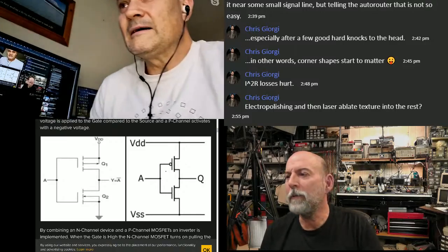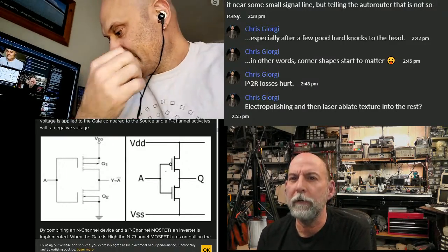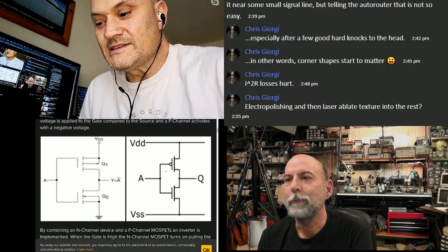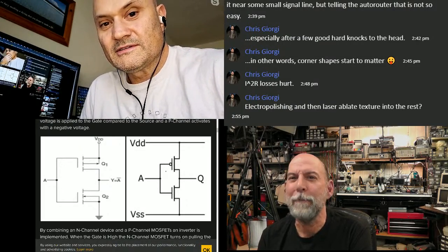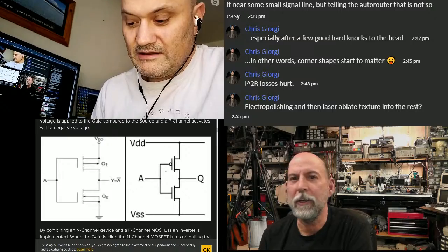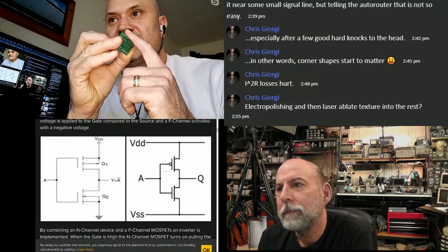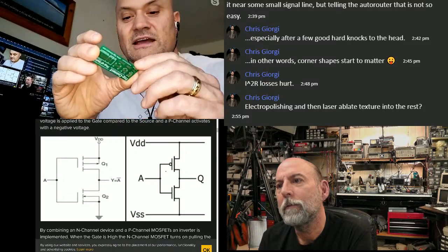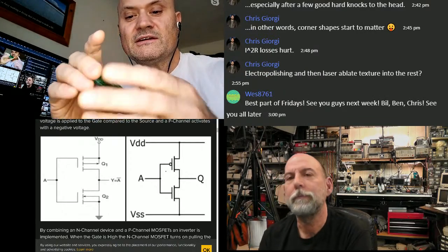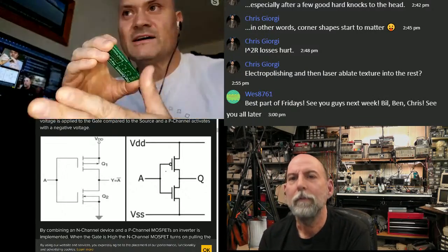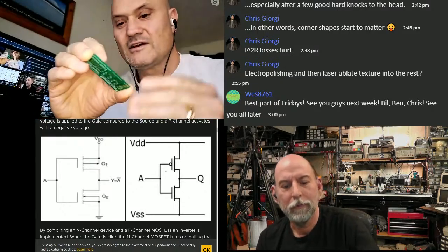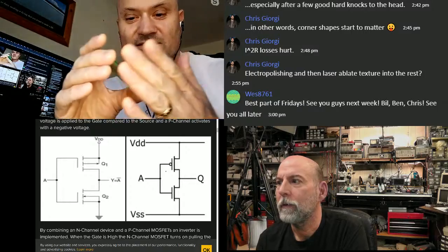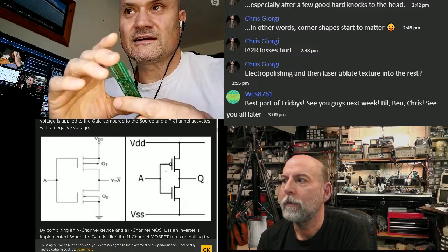So why wouldn't we use the edge of the PC board for a reference? Because the machine that cuts out the PCBs will be all over the joint. They're sloppy. Yeah. So you might be machining that and it'll be nice and smooth, but the bit can wander, and you might be excising the board by a guillotine. If it's a cheap low-cost product, you can, and some boards can be guillotined.